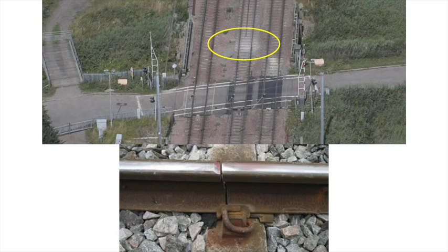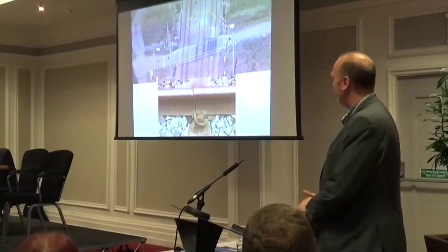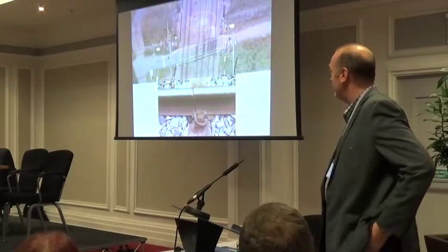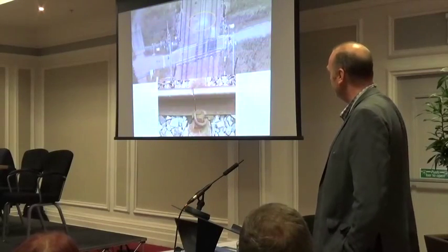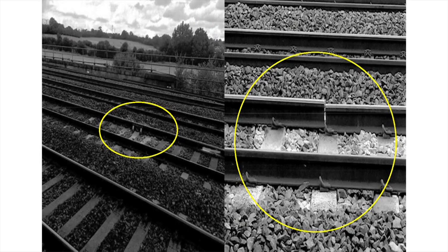You go back, there's another location, but the picture in the database shows a typical foot failure. Pad condition isn't great. A fairly clean vertical break through the rail. This is one from very recently. Broken rail, again foot failure, clean break. A lot of people look at them and think they're not that risky. You can already see the misalignment between the rail ends that's occurred there.